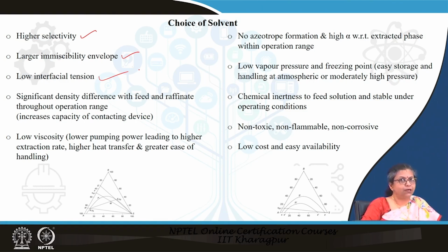Here also I would give you some particular caution. See, suppose the droplets have become very fine, very emulsified, then in that case coalescence becomes a problem. But after the extraction has occurred, we would like the droplets to coalesce and either settle or rise depending upon their density relative to the continuous phase density. So, we would not want very fine droplets, at the same time we would like a proper emulsion. So, a more or less low interfacial tension is necessary.